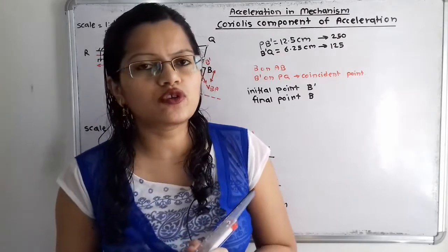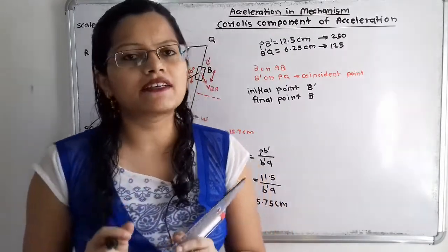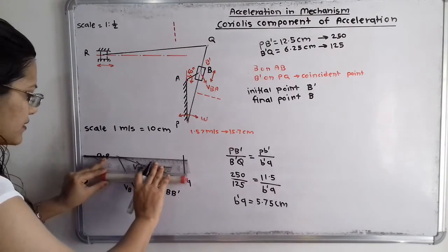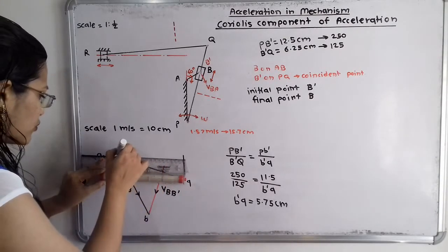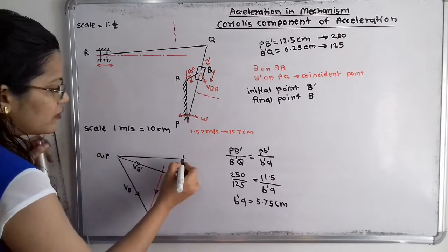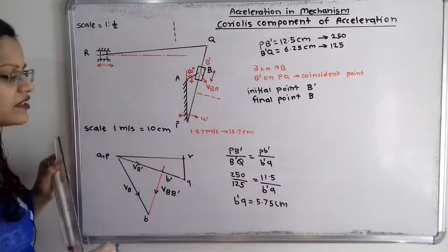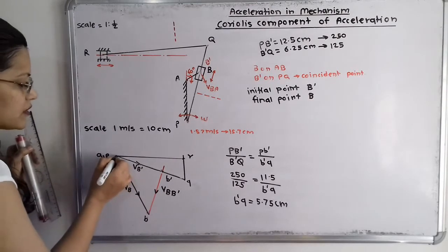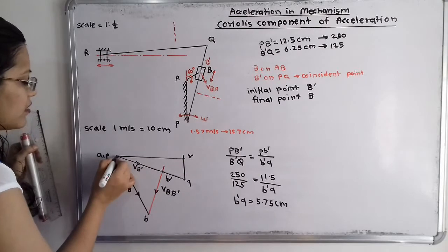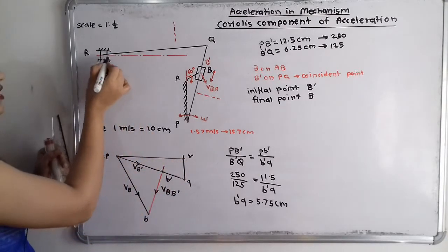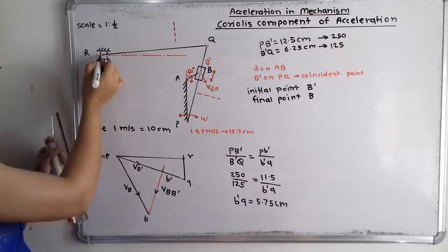So we have to draw the horizontal line passing through the fixed point. So I will draw here one horizontal line passing through this point A and P. And here is the point of intersection, and this point of intersection is nothing but the point R. So if we observe, this vector AR, or we can say PR, indicates the horizontal motion for this ram R.